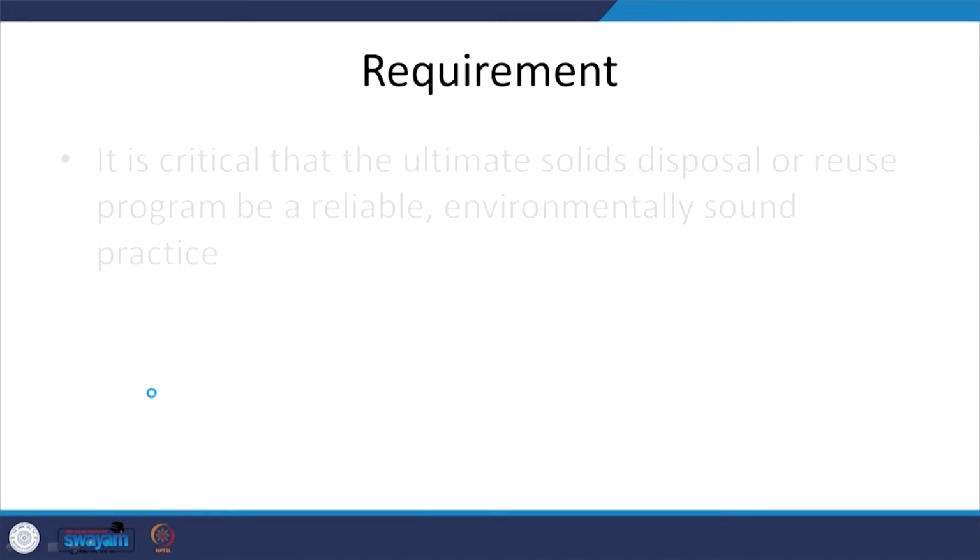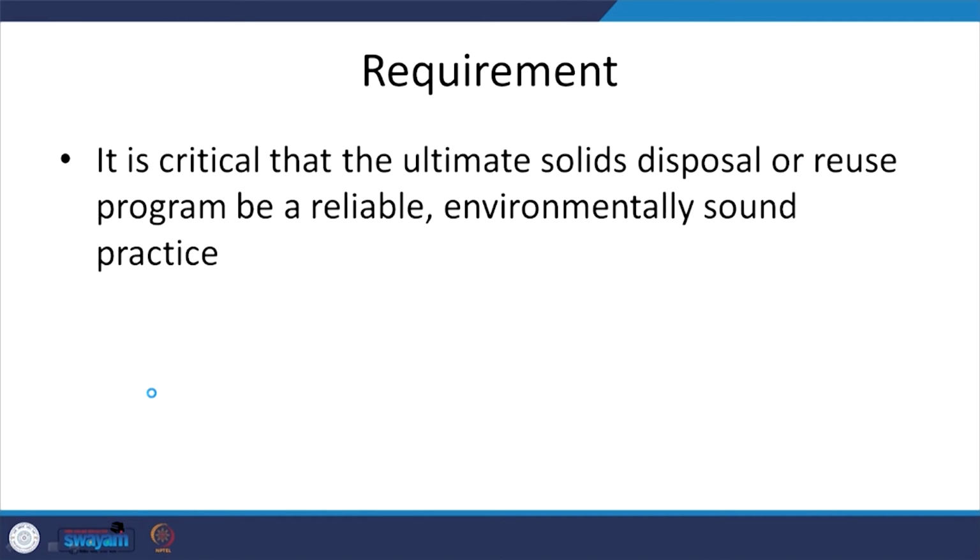So, disposal. Now that I am done with it, where can I dispose of this dewatered stabilized sludge? Depending upon the kind of source and the kind of contaminants, as in if it has remarkably high strength, different ions, or God forbid heavy metals, then obviously you can't dump it into the agricultural field.